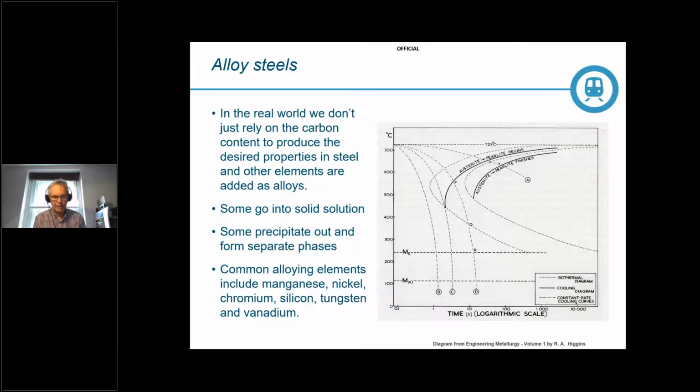And the result, as we know, is a tough austenite, which during service, when subject to abrasion and wear, has the effect of changing the outside surface to a very hard martensite, which is very wear resistant. It does have its drawbacks, however. It's hard to drill or machine because of the work hardening ability, and recrystallization will commence at around 260 degrees C, allowing carbon diffusion, and thus great care is needed when carrying out welding of manganese steels.